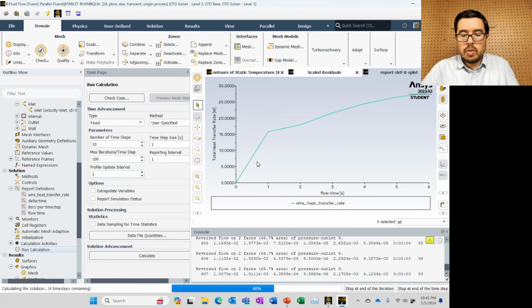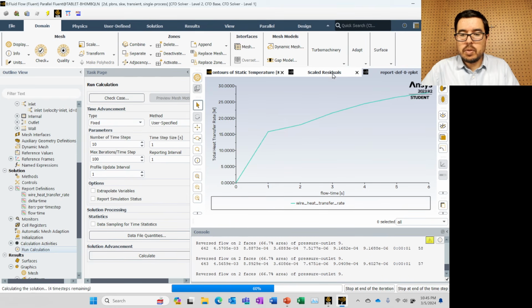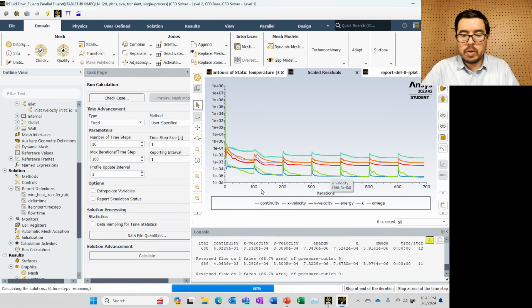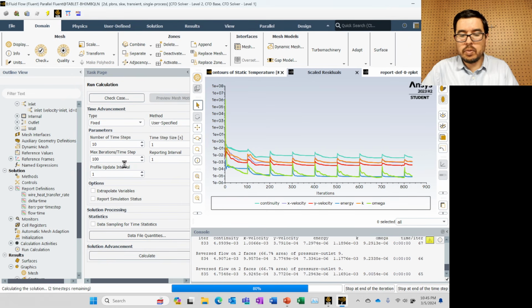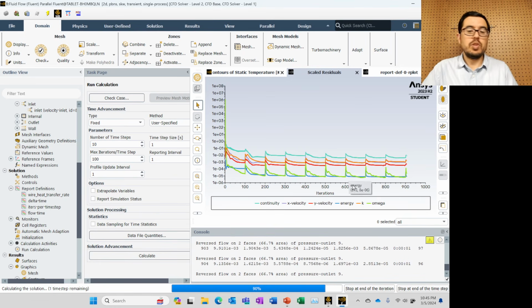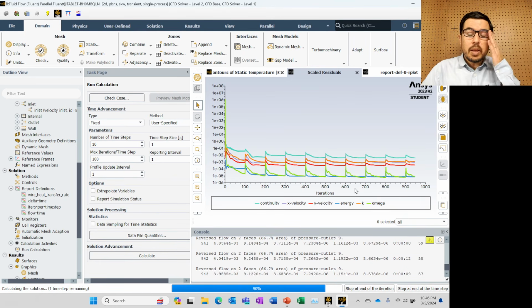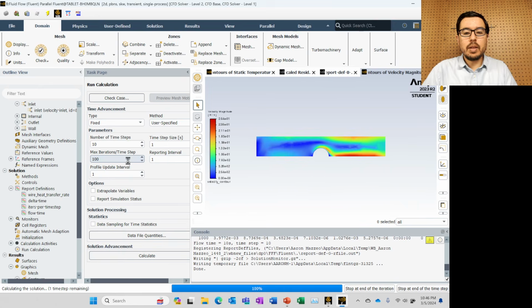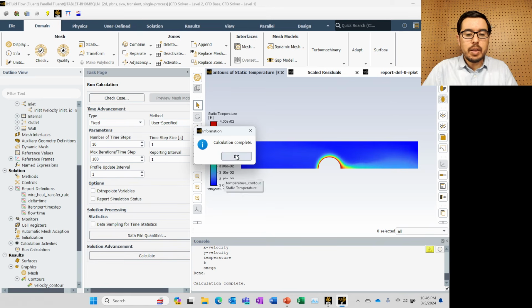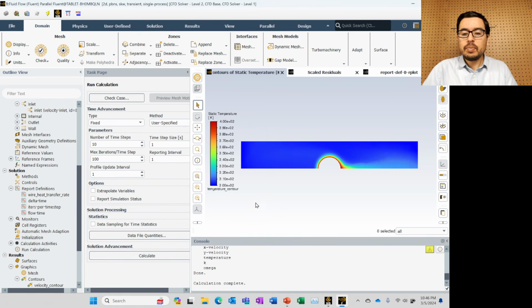So this is running for a little bit. The residuals. Okay, so we're running 10 seconds, 100 iterations for every second, essentially, is what we've got. That's the max number of iterations per time step, and we're hitting it. So maybe we would want to change things for another simulation so we don't just get to our maximum every time.